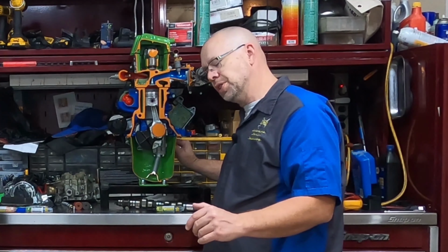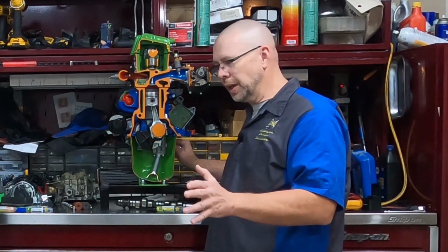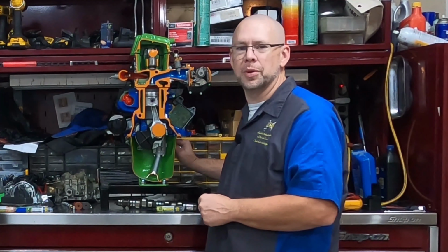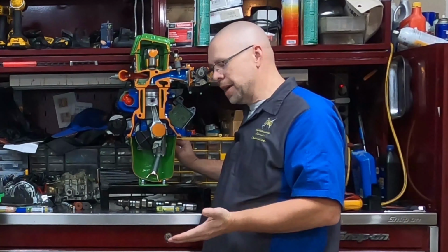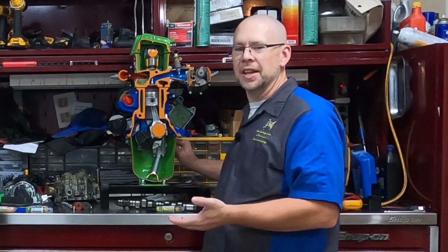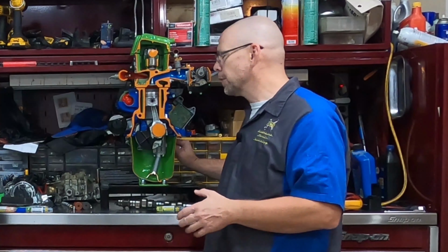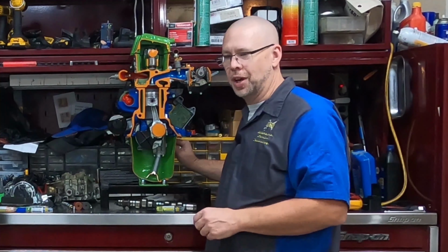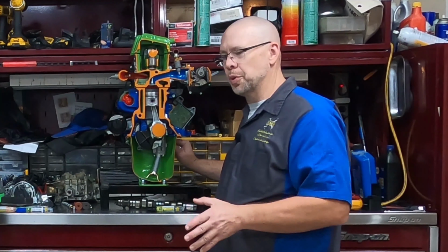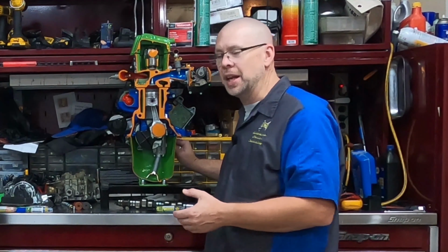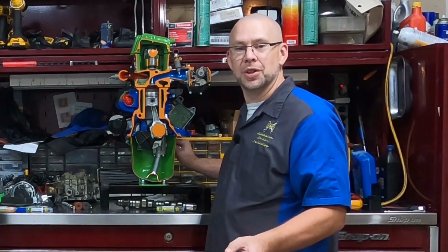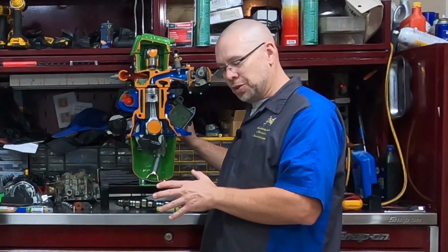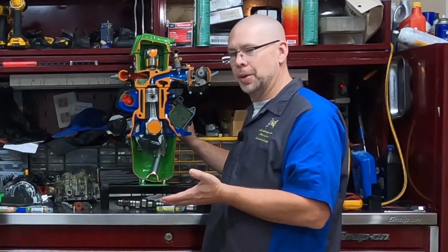We'll discuss those in the future, but that's just one thing we have to be aware of. Any increase in cylinder pressure, timing has to back off or be less advanced. Very rarely do we time an engine after top dead center, which we would term as retarding the ignition timing. Anytime we take the ignition timing back from where it is, that's retarding the timing. See the terms video. Anytime we build extra pressure, we have to back the timing off.